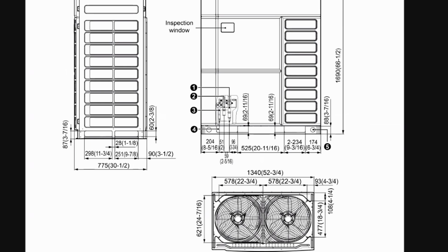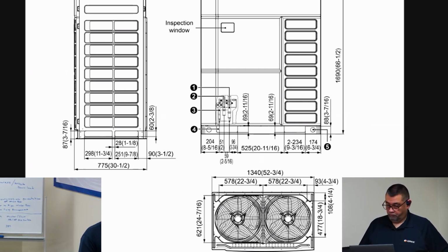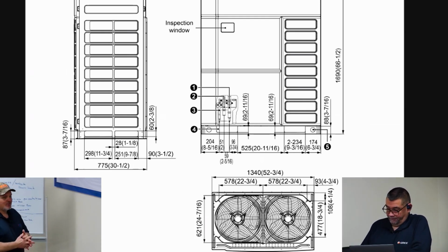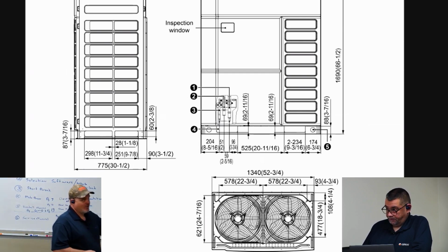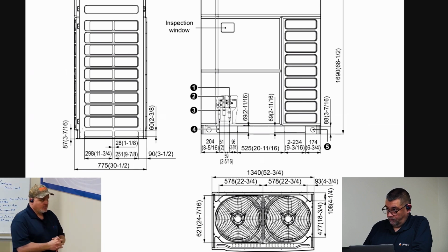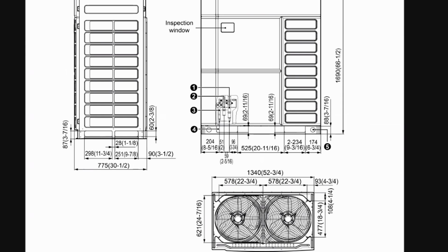I hate saying this sometimes, but I'm pretty sure I'm right. GMV5 was not the same. You used the far left and the far right. So kind of an FYI to everybody, this is the only place it's dictated in there. And I'm working on getting that uploaded into the service manual as well. I would rather just have a picture like this right here, clear cut heat pump, and then another picture, heat recovery. Heat recovery, yep. So it's very clear. Anyway, we want to make sure we pointed that out.